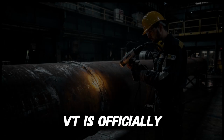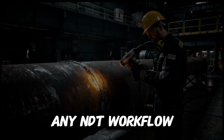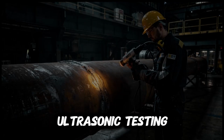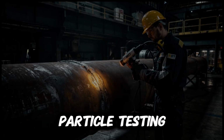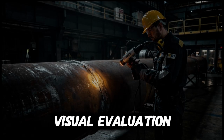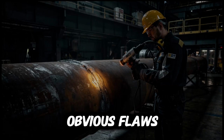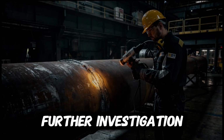Today, VT is officially recognized as the first step in any NDT workflow. Other methods like ultrasonic testing, radiography, or magnetic particle testing are rarely applied without a preliminary visual evaluation to rule out obvious flaws or to identify critical zones for further investigation.